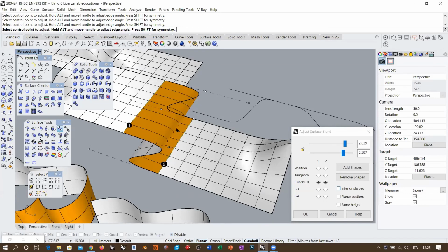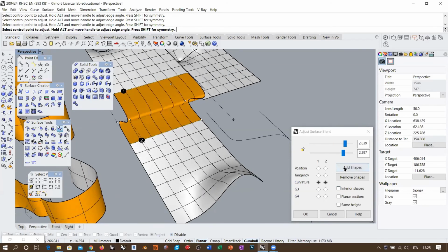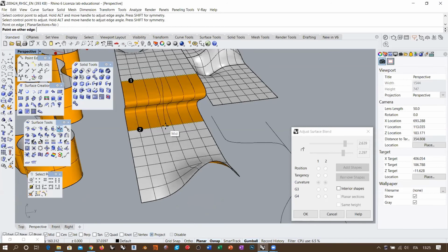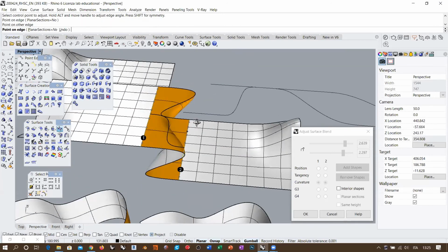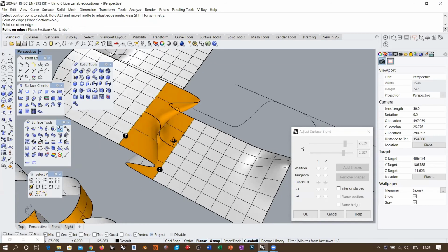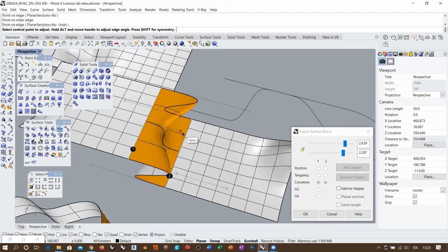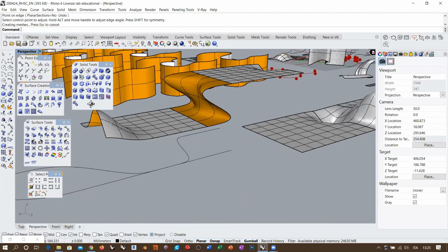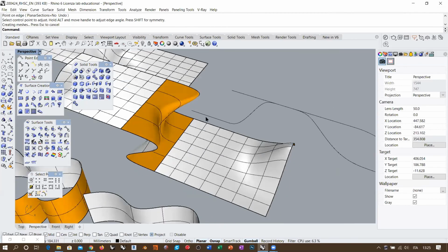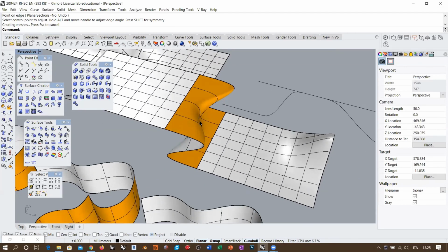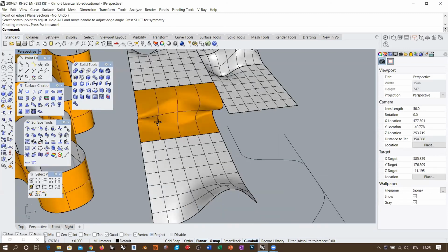If I remove the interior edges and I only add a shape like here in the midpoint, for example, now I have control over one single cross section besides the initial and last cross section. So let's say I create this blend surface here, okay, which is quite complex already. And it's very difficult to recreate it, okay, unless I know exactly what I was doing.